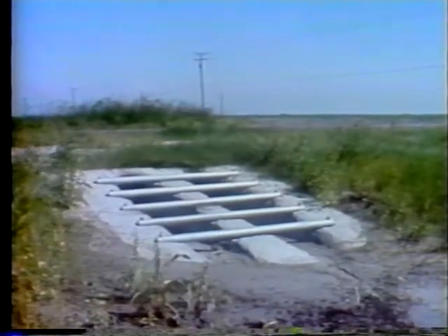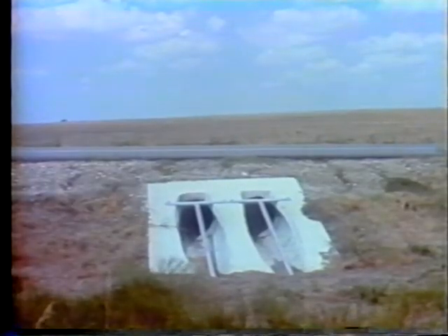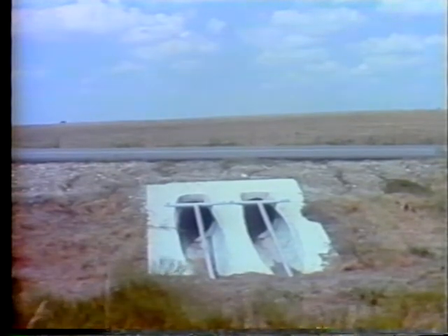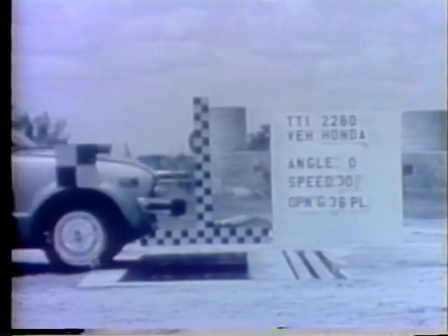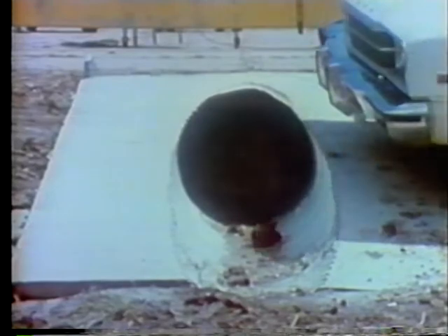Large culverts may require pipe runners or grates perpendicular to the dominant direction of travel. For example, research has shown that culvert openings up to 36 inches in diameter can be safely traversed by both small and large cars. Therefore, in most instances, transverse culverts with a diameter of 36 inches or less could be designed to match the side slope and not require a grate. Transverse culverts greater than 36 inches in diameter would require a grate.